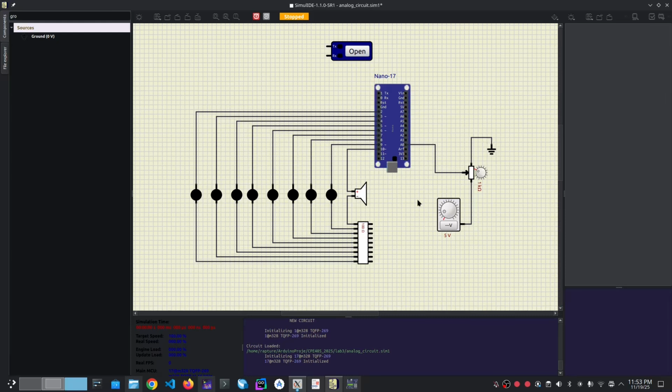Okay, we're almost through with the circuit design. So let me also connect my serial terminal here. The serial terminal is connected. The receive portion goes to the transmit portion of the Nano. So the transmit from the terminal also goes to the receiving end. So that's the circuit, and then I will make the last part of this. I have my circuit here. So I ground the remaining pins to have the full circuit connection.